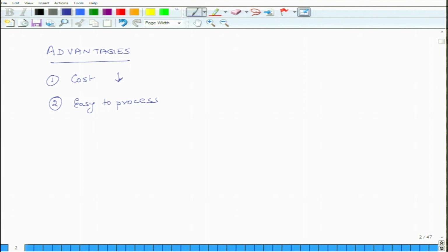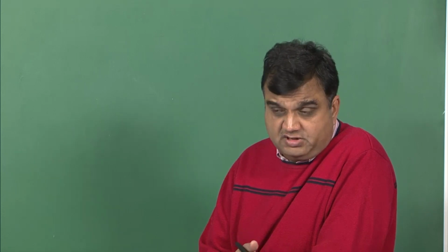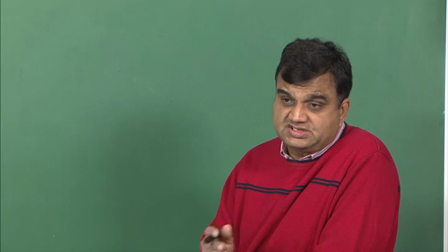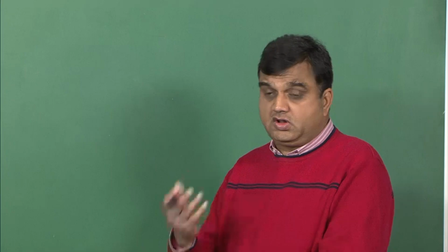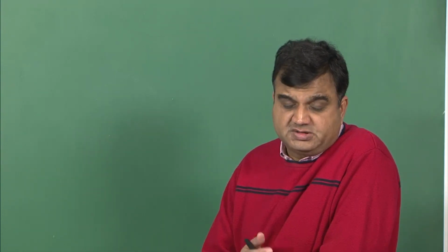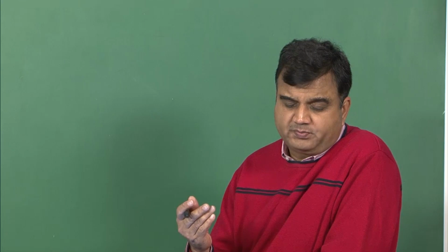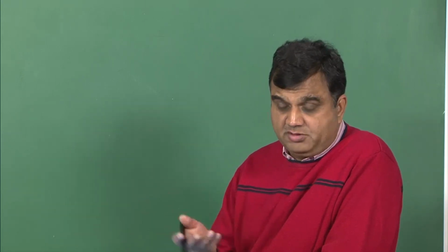Again, easy is a relative term. Third thing is, the density of metal based matrices is pretty high. So, suppose you want to use aluminum as a matrix material, its density will be 2.78 specific gravity. But a lot of these plastics, their densities are much less. So, they are in the range of somewhere between 0.8 to 1.5 or something like that. So, they are lighter, and what that means is that if you use these types of matrix materials and mix them with fibers, the specific strength and specific stiffness will be high because the density is less.